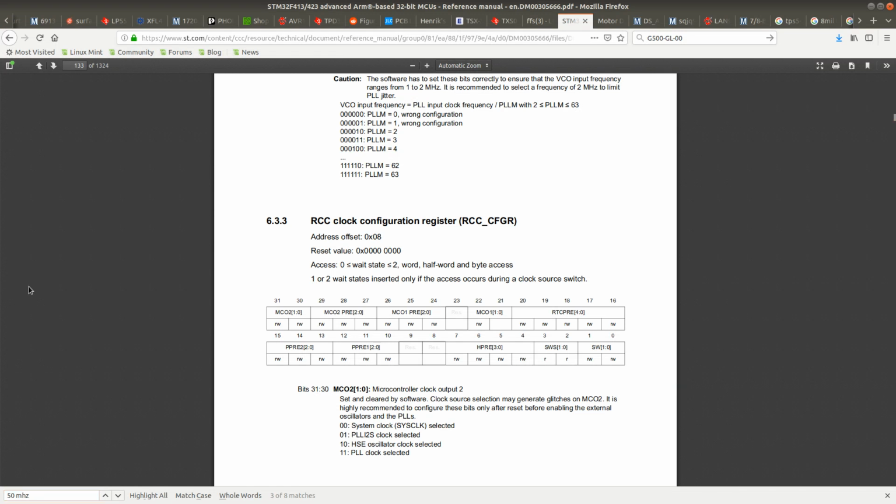Which is something I do need to figure out, because if I want to change the clock speed while the processor is running, for example, to save energy, then I need to have a working solution for the scheduler, so that it doesn't suddenly start running slower or faster.